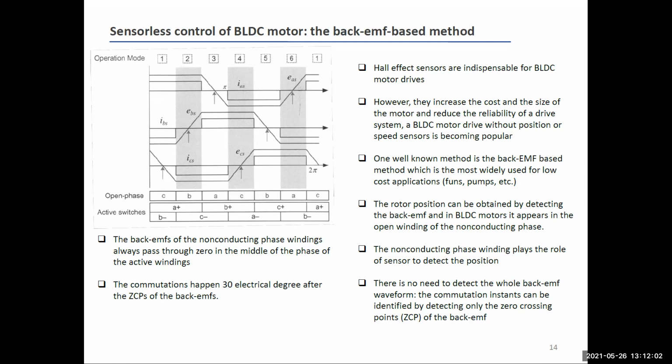Okay, so this is a sensorless control of BLDC motors that makes it possible to operate the brushless DC motor without any information about the position, so without any Hall effect sensor. How can you evaluate this back EMF? By the back EMF appearing at the phase of the motor.